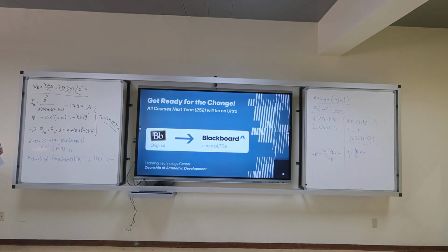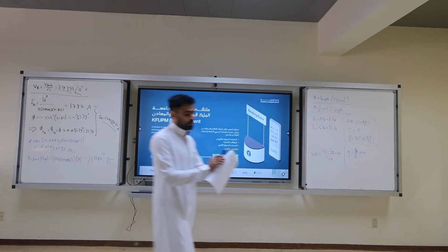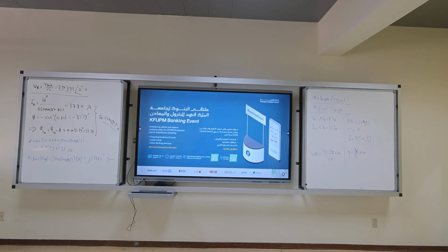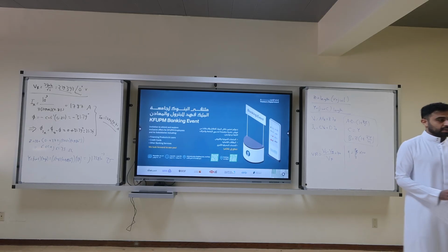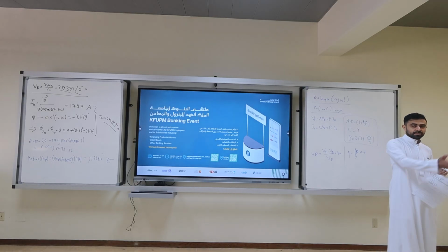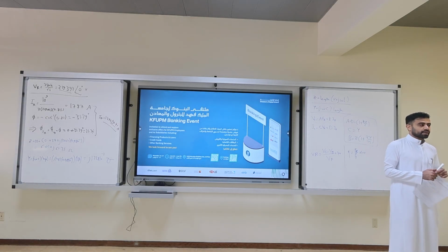Doctor, why the length 180? We didn't multiply by 10 to the power 3. Because I told you, it's written here, it's ohm per kilometer, and I told you in the class, don't multiply by this. Watch the video. So you didn't watch the YouTube. Did you watch it? If you watch it, you remember I said do not multiply by 1,000 meters. It's ohms per kilometer, not ohms per meter. That's why we have fake quizzes. See the benefit of the fake quiz? Okay.